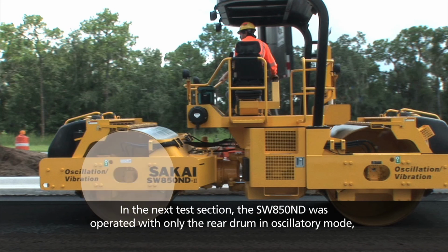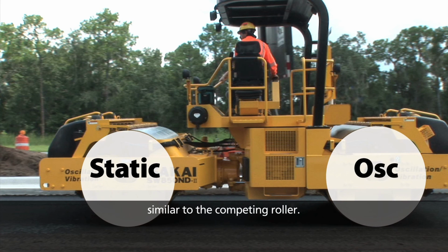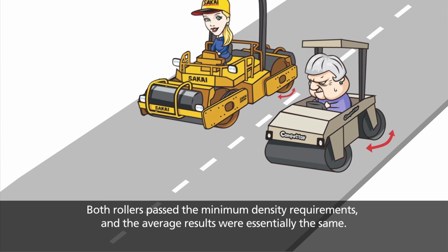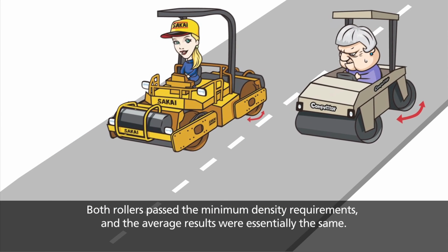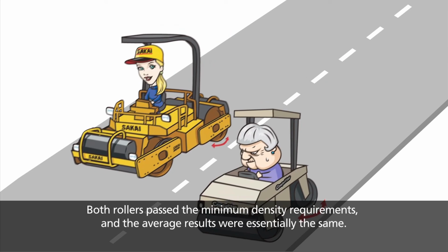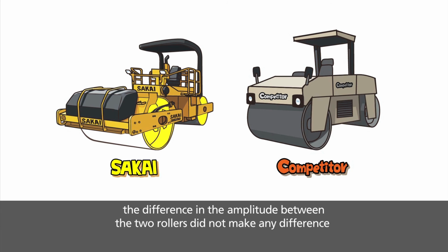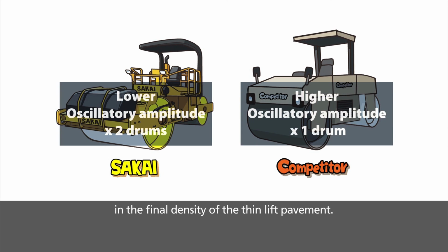In the next test section, the SW850ND was operated with only the rear drum in oscillatory mode, similar to the competing roller. Both rollers passed the minimum density requirements, and the average results were essentially the same. Even though the SAKAI ND roller operates with a lower oscillatory amplitude, the difference in the amplitude between the 2 rollers did not make any difference in the final density of the thin lift pavement.